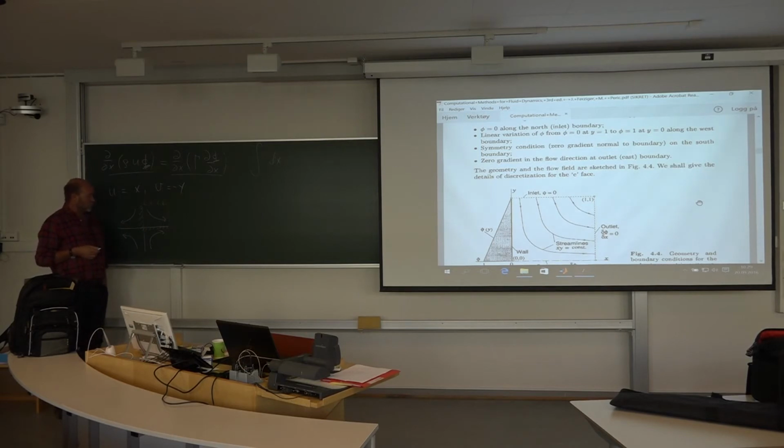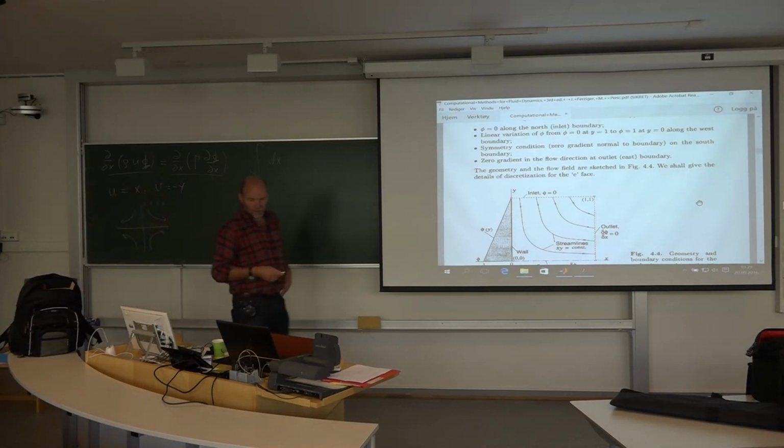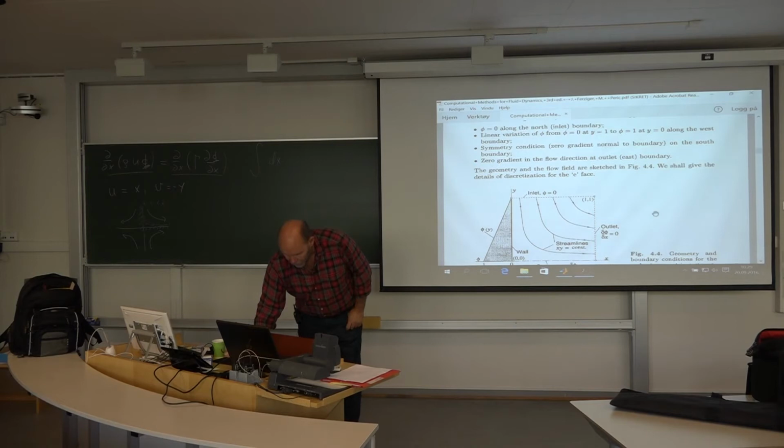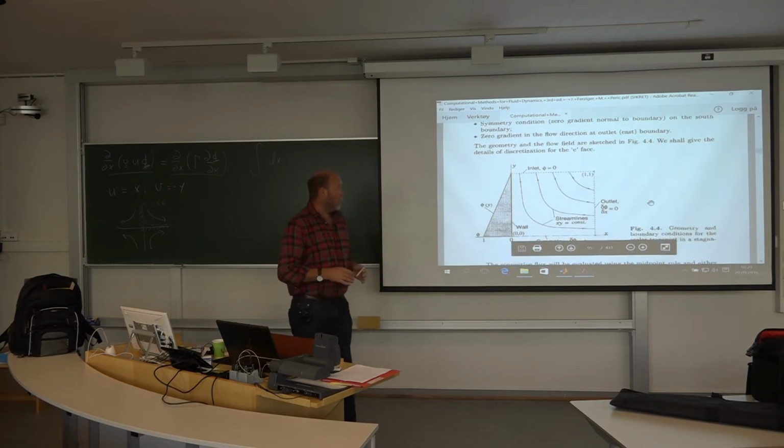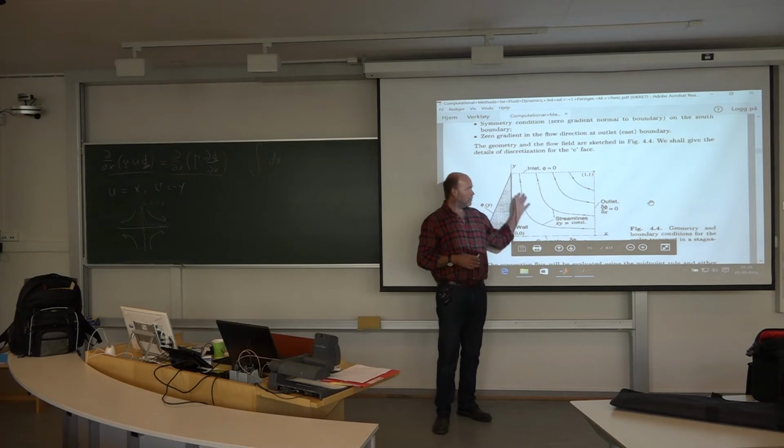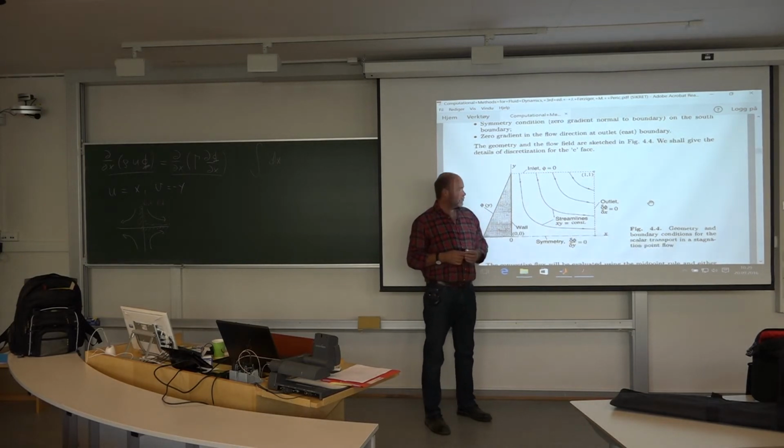So we should suspect a solution with mostly zeros of this phi, but you will have something more and more alongside this left wall, and then due to the flow it will be transported out. So we will have some phi in this manner. Just as I say, the velocity field is known. We know the streamlines before we begin. It's just this concentration we don't know.